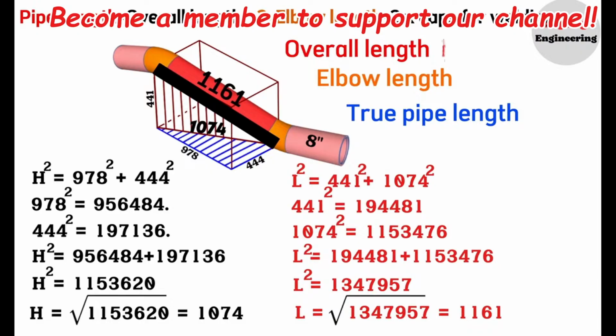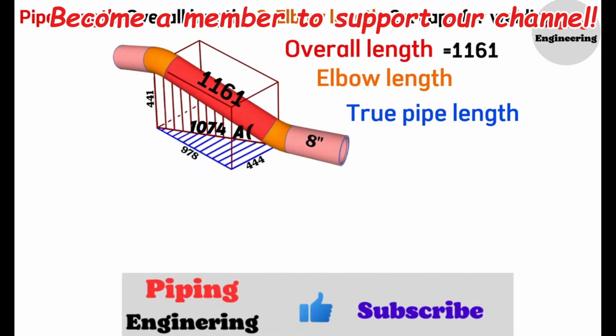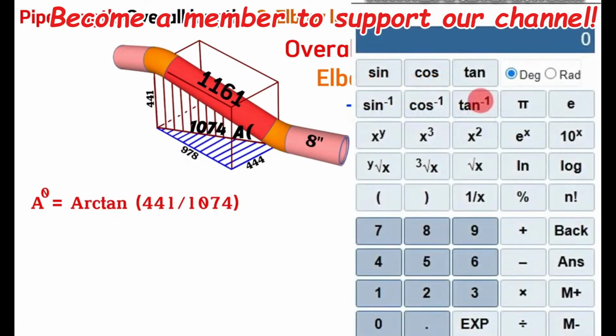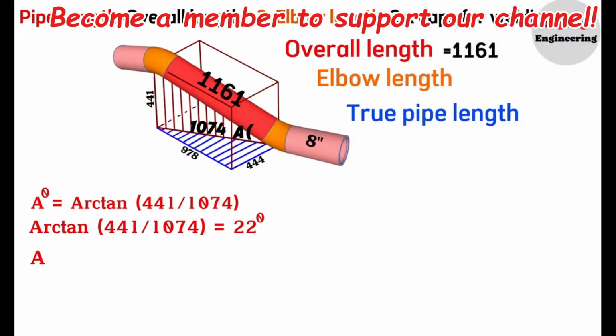So, after our calculation, we will now use the trigonometric function. If we denote this angle as A, then A degrees will be equal to the arctangent of 441 divided by 1074. Using a scientific calculator, the arctangent of 441 divided by 1074 will equal approximately 22 degrees. So, we calculated and found that the cutting angle of these elbows is 22 degrees on the 8-inch pipeline.